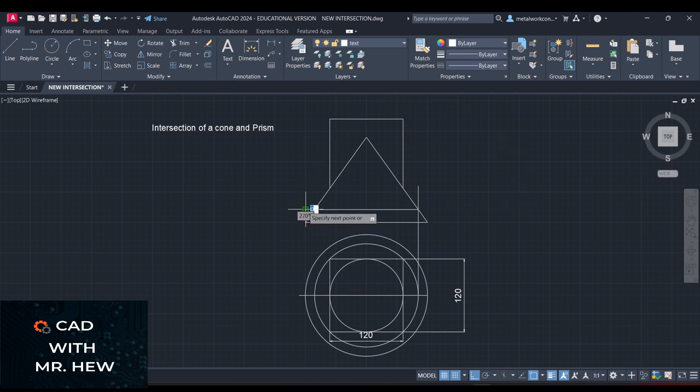All right, let me trim off the excess lines. These are construction lines. If you were using the traditional instruments such as a T square and set square, you would let them stay, because those lines would be drawn with a 4H pencil and they would represent construction lines. All right. So this disc will be the lowest point on the prism, right?